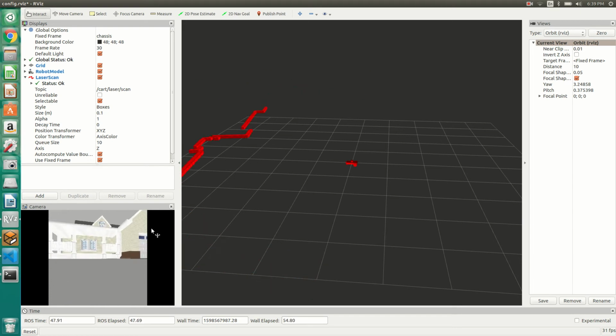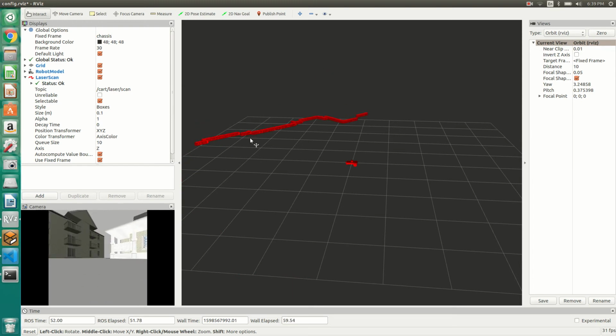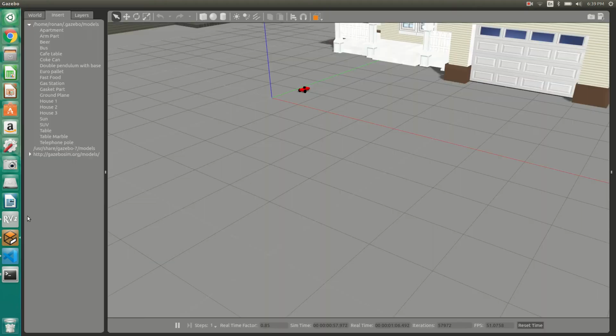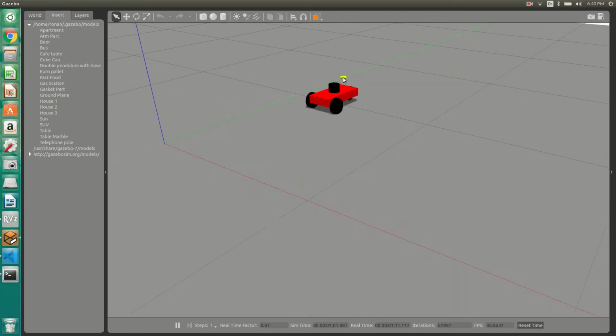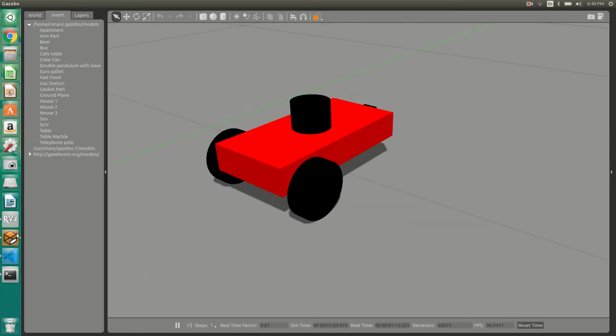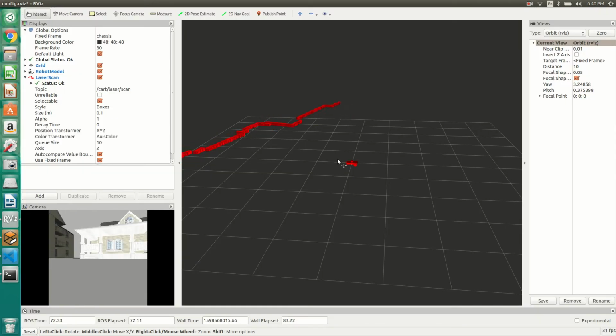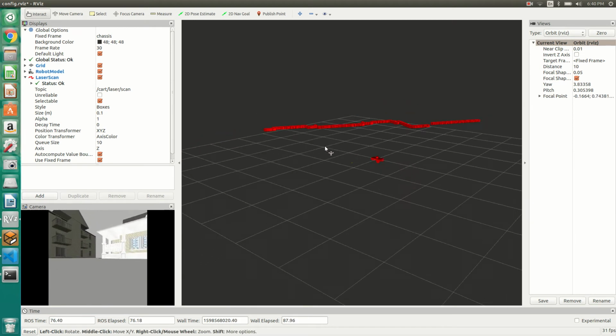car. And then at the center of the screen, you've no doubt noticed all these red dots, which are the graphical representation of the LiDAR data that's coming in from Gazebo. There's a LiDAR sensor I have represented by this black box here on top of the car. It's simulating LiDAR sensors spitting out laser output and getting reflections back from objects. And it's being processed and giving the user a good sense of what is going on in the environment.